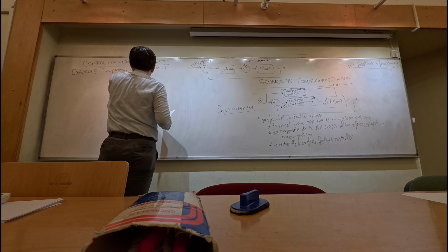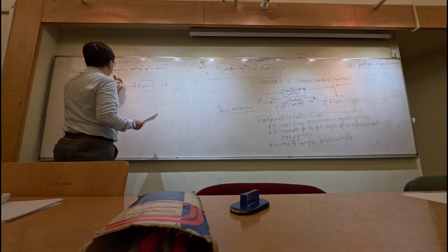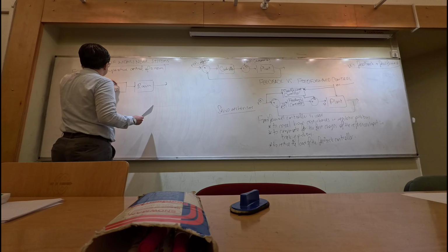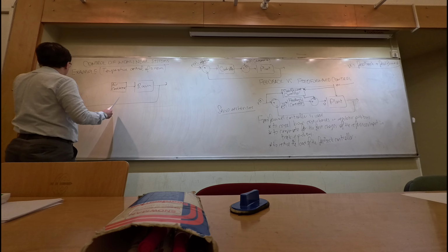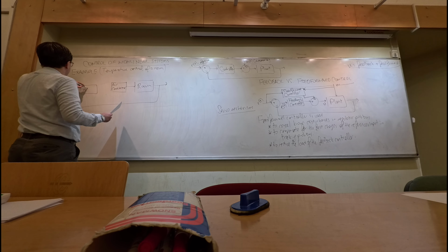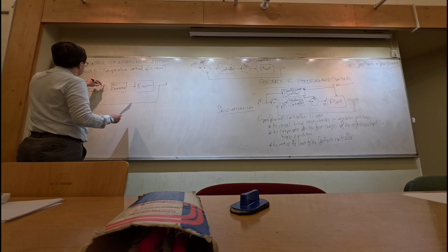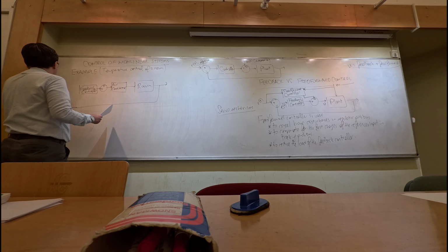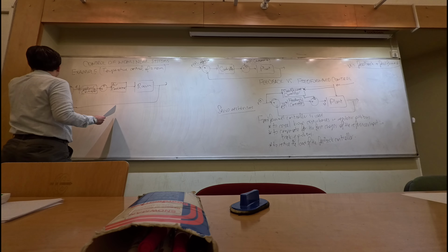In this case, we have the system that we would like to control. It is the room itself, and we have our actuator. So this is an air conditioner. And we have a feedback controller here, which gives input to the air conditioner. We have our feedback loop, and this feedback controller takes the error signal, and we have the reference R of t.